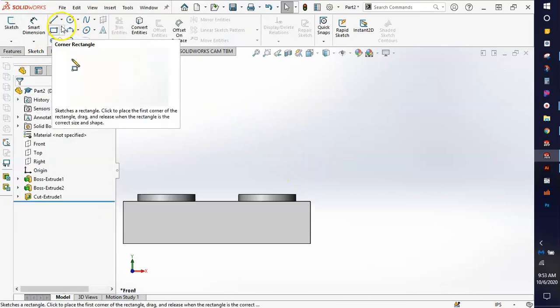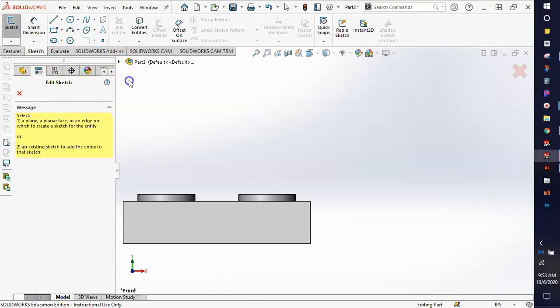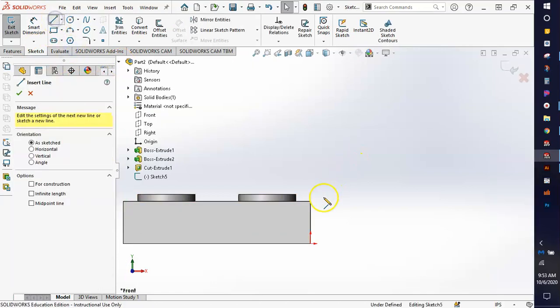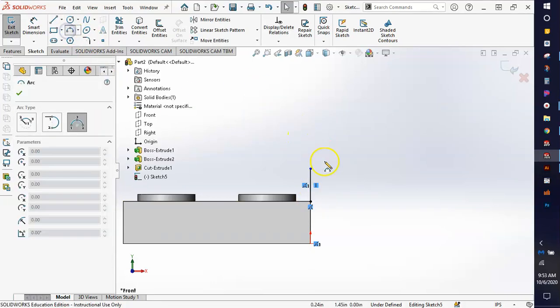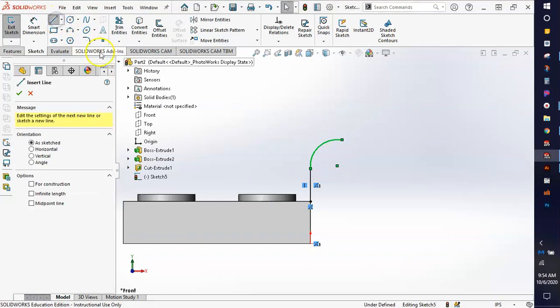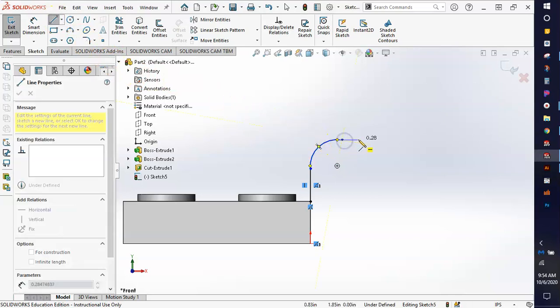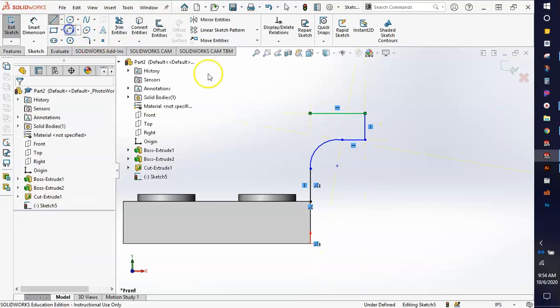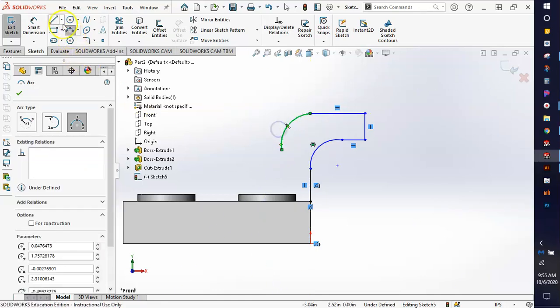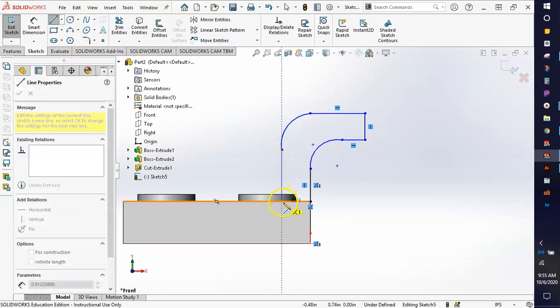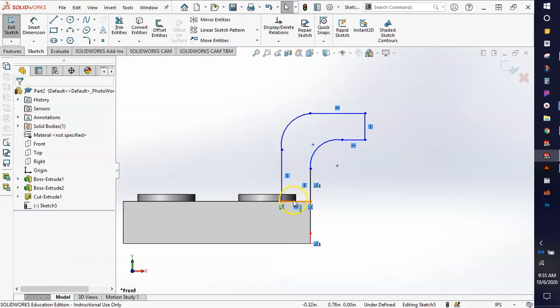I backed way out here. So you could just get the line tool and then switch off and go to the arc tool. That was the 3-point arc tool, by the way. And then I just got my line tool, and I'm going to continue over straight, back up, over again. Again, get your 3-point arc tool. So you see that line tool, I think doing that is a little bit faster. And then connect that over. So don't forget to draw that bottom line there.